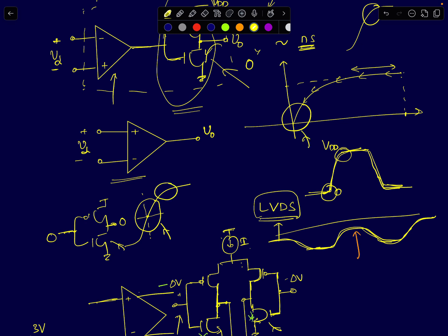Now, whenever you are close to the supply rails, whether at logic high level or logic low level, whether it's the charging path, where charging happens through the PMOS, or the discharging path through the NMOS, your transistors will be in the linear region. When it is close to the supply voltage and the PMOS is still charging, the PMOS will enter the linear region, and in the discharging path, the NMOS will enter the linear region. In the linear region, the devices have lower current to either charge or discharge the nodes. So most of your rise and fall time comes in this region, because this is where the devices are really slow. They are really fast in the other region.